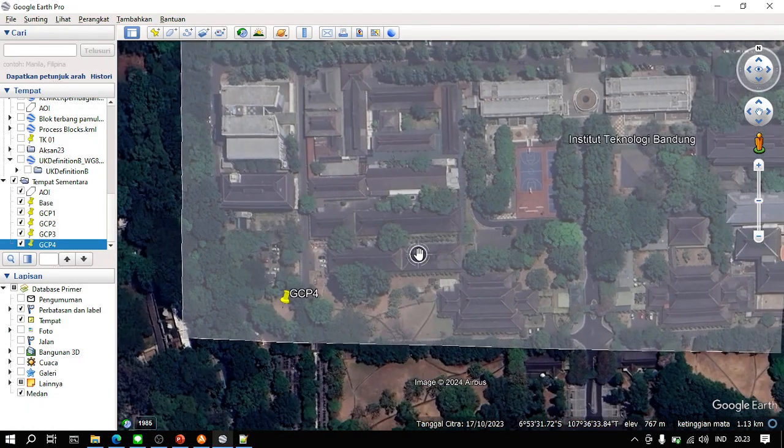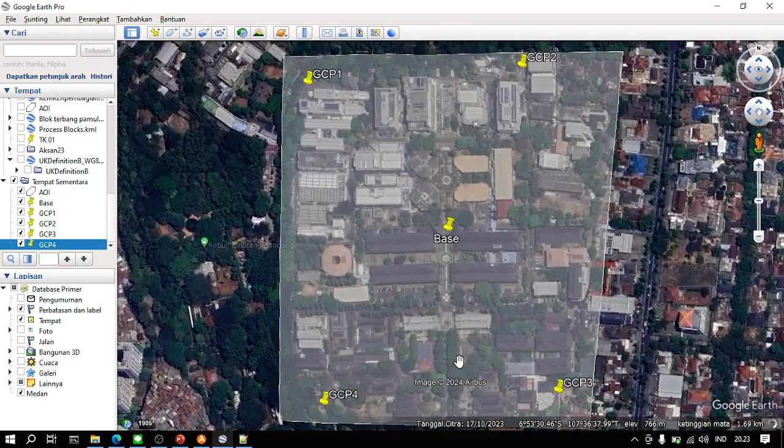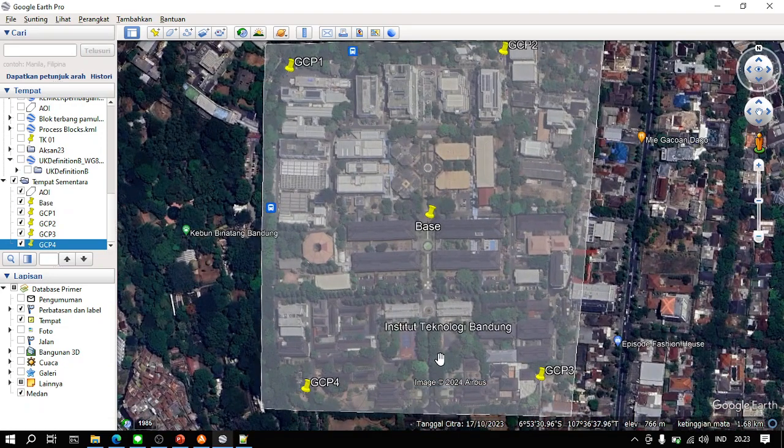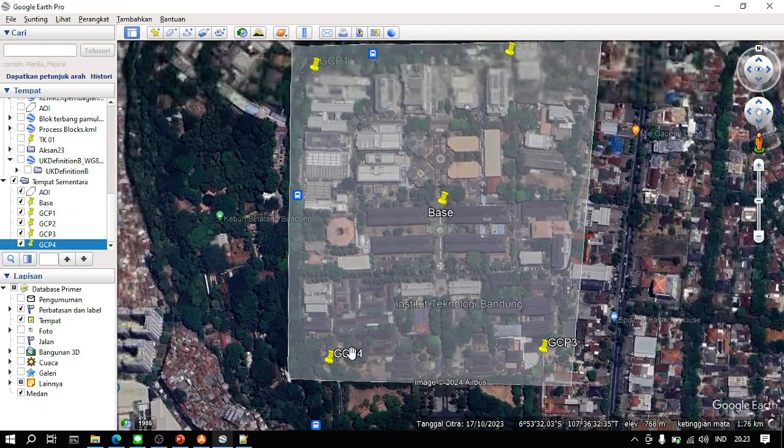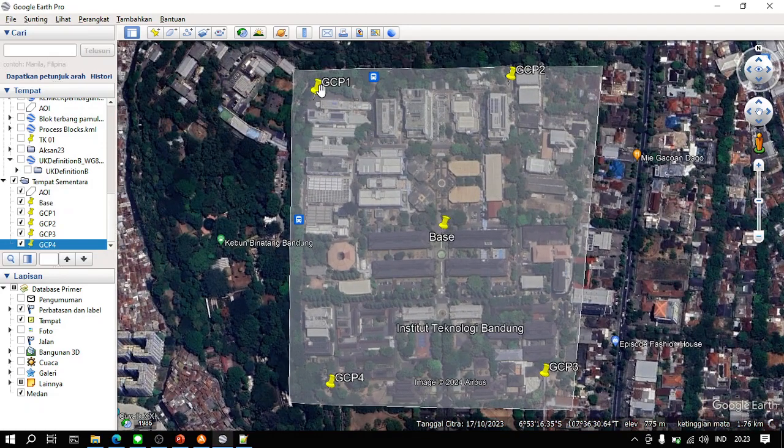Okay. So those are the requirements for placing a control point. It should be where you can actually put a point. For example, if you measure your GCP by GNSS, you need to put your points where you can actually do GNSS measurement. So you need to have a clear view of the sky, and it's not obstructed by anything. You're also not obstructing anything. That's also important. So don't put it in the middle of the road, for example.